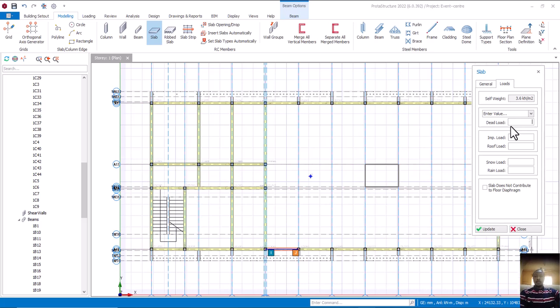What additional dead load is going to come on top of the slab? Any other load in terms of dead load other than your tiles and your partition load. When it comes to tiles, the tile load is 1.2, either tiles or terrazzo, whichever one is 1.2. Then our partition load is 0.5. So if you now add 1.2 plus 0.5, it gives us 1.7.